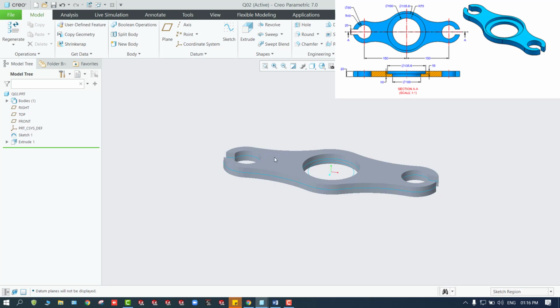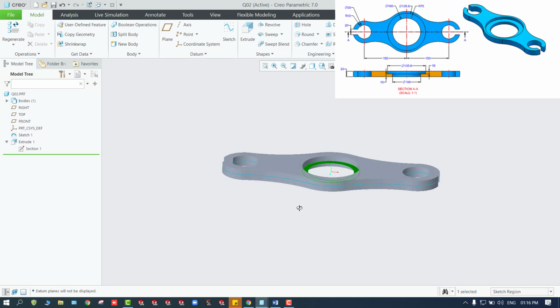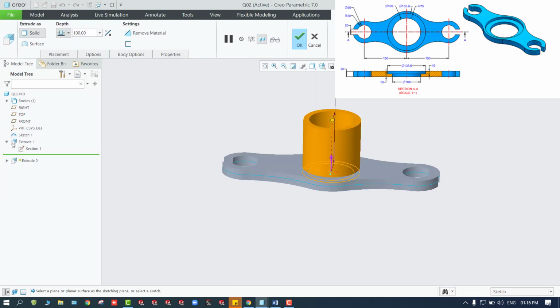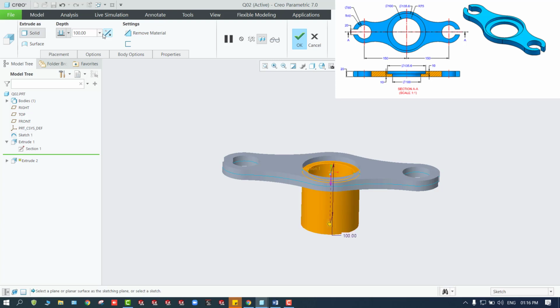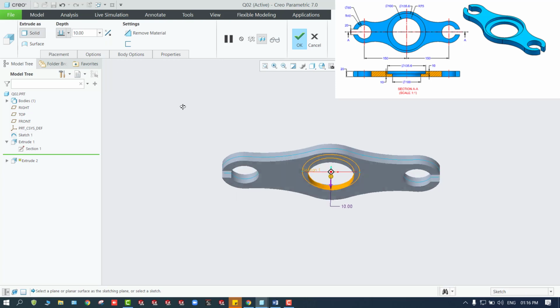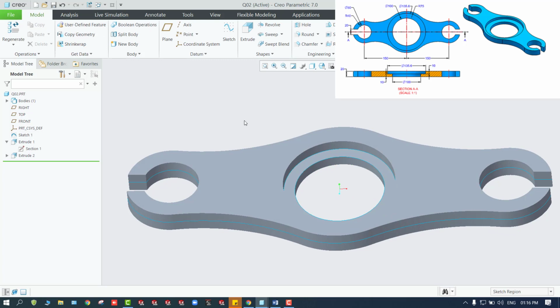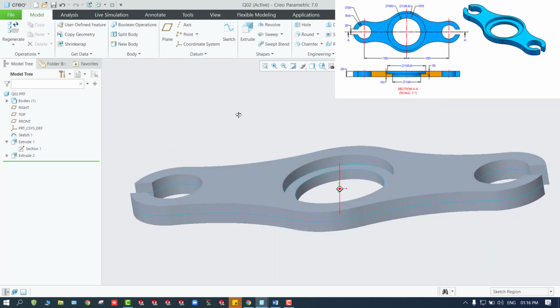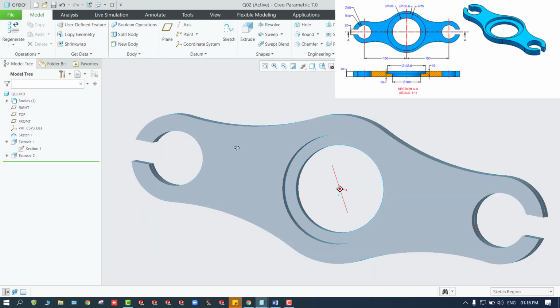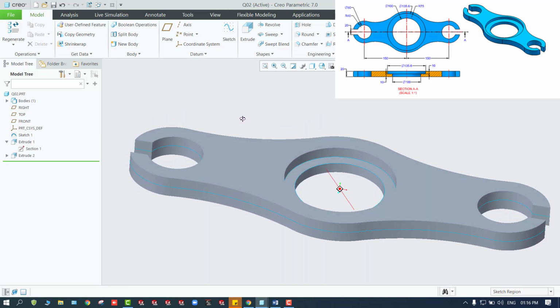You can hide all the reference entities, and here this region into extrude. Anyway, this sketch region is selected. That should be towards the bottom itself. Here I'll change the direction downwards and mention it as 10. Yep, as you could see, this is what I'm looking for. But as per the image, the dimensions at the center are not matching. So I need to edit this particular sketch.